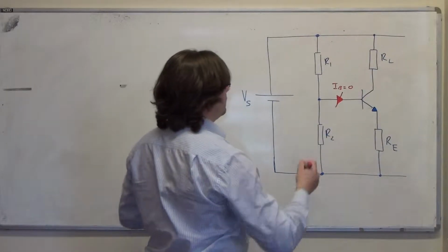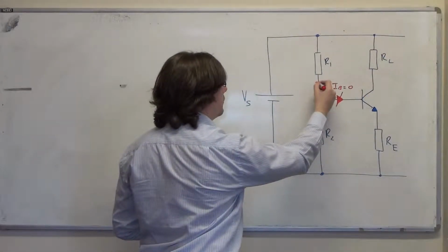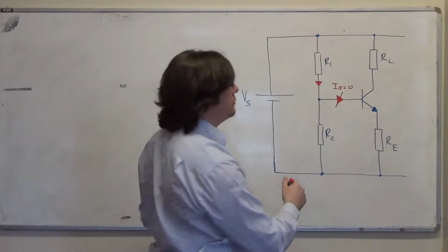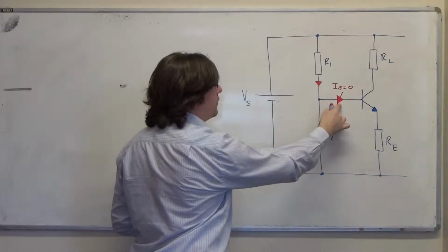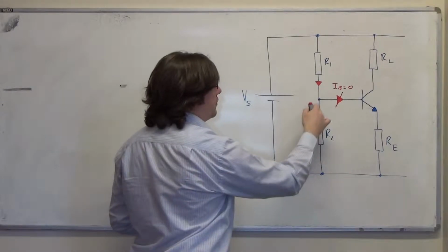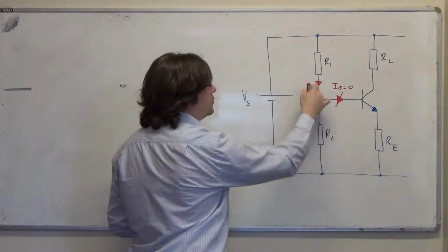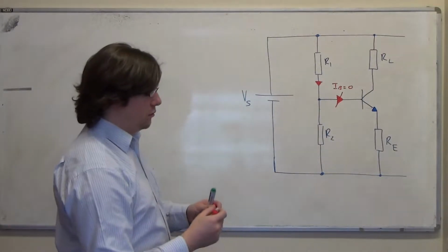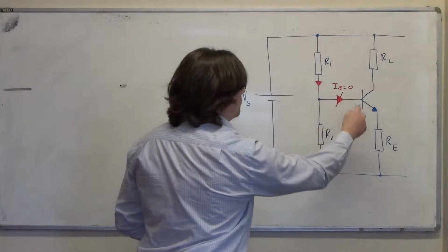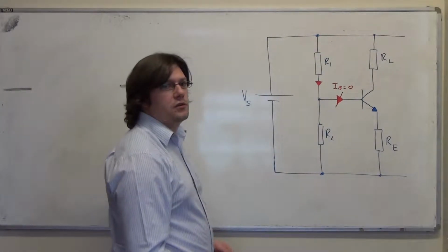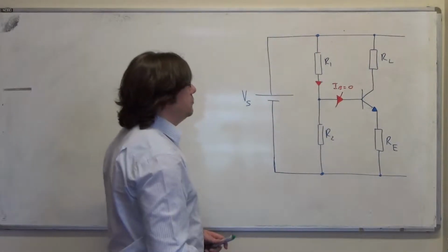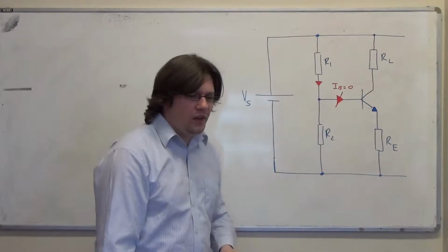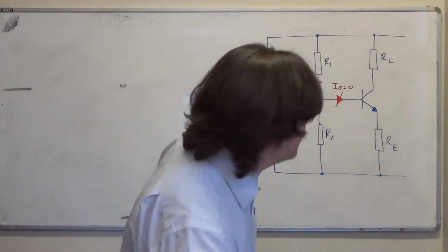So what we also need to do is make sure that the current flowing down here through R1 is so large compared to whatever the real base current is. Obviously it's not really 0. This has to be so big compared to that, what does actually pass down here in the R2 is not much smaller than what flows through R1. And if that happens, that's another way of saying, well, look, IB is so small, it doesn't matter. So HFE is much greater than 1, so IB is insignificant for transistor operation, and the current in R1 is so big that whatever little IB there is doesn't make much difference to the overall value. And not much difference is sort of 5% or so.